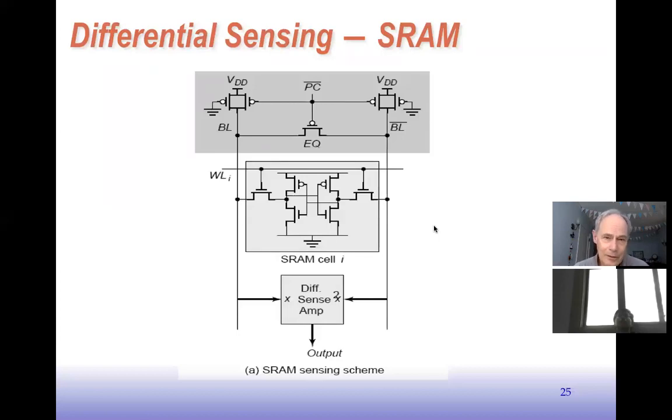So SRAM is the type of memory that you'd see most common in chips like microprocessors and other signal processing chips, GPUs and the like, because if we need a large amount of memory on chip with the processor, like for instance, cache memory or register files, perhaps we can use this type of memory because we can build it out of standard transistors, the same types that are there for building the logic circuits.